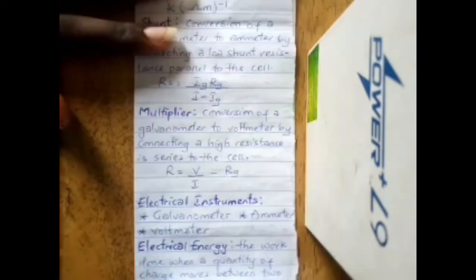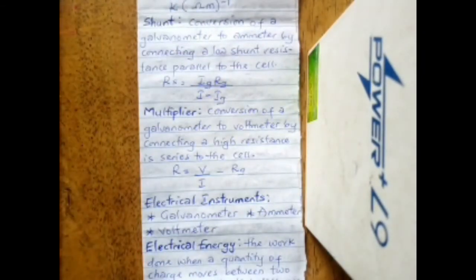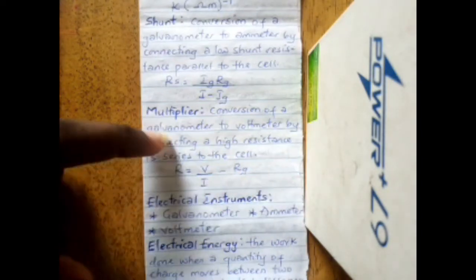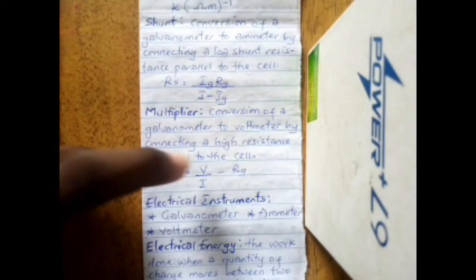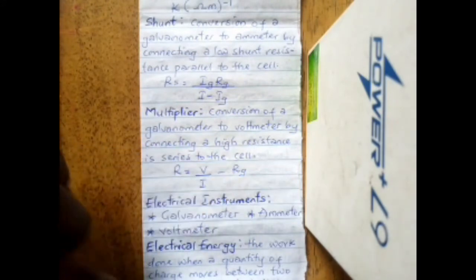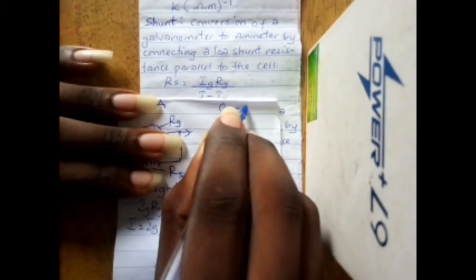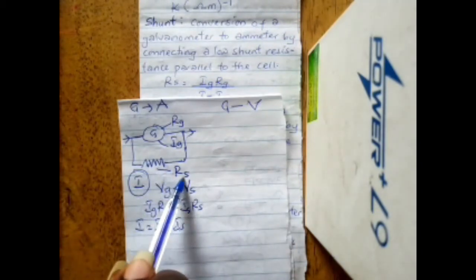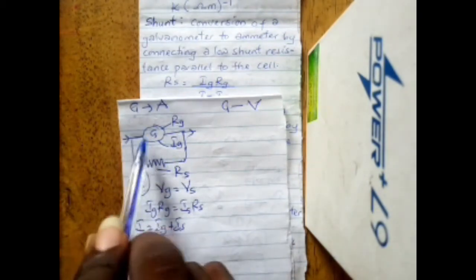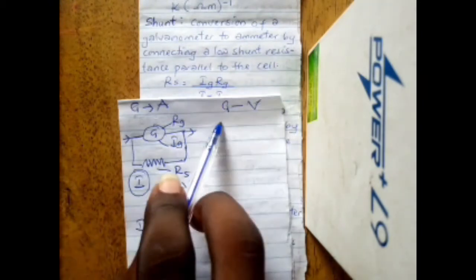Now, to convert a galvanometer to a voltmeter, a voltmeter measures voltage, which is potential difference. You simply connect a high resistance in series to the cell. Now, for the first case, you want to convert a galvanometer to an ammeter. You connect a low resistance, which is known as a shunt, in parallel to the cell. But now to convert a galvanometer to a voltmeter,